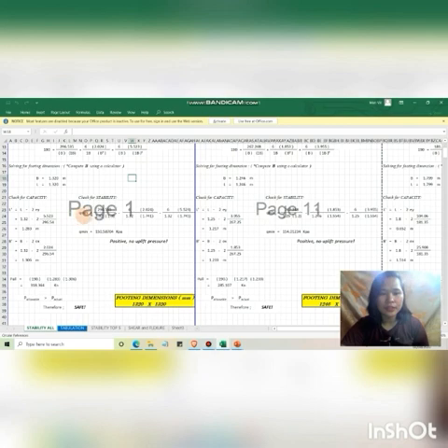So substituting the values, Q mean is equal to P total over the product of our dimensions, minus 6 Mx over length and B squared, minus 6 My over base times length squared. So we arrive at the answer for our Q mean equal to 150.58704. So it is a positive answer. Therefore, it is safe and no uplift pressure is present with our footing.